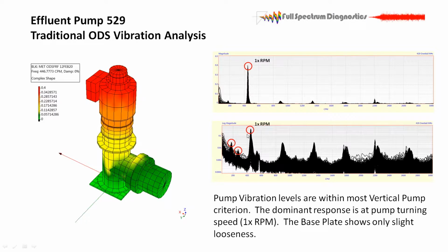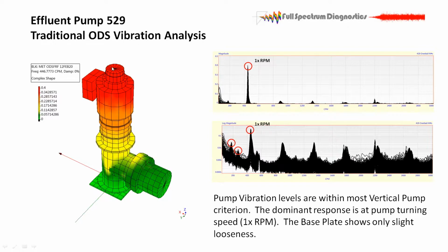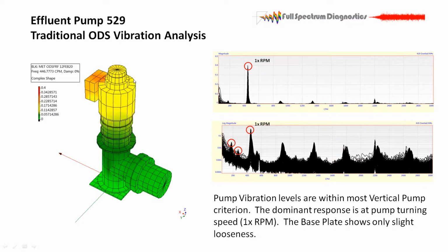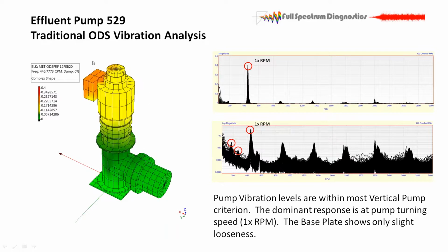So I think there's a natural frequency in here. That's one indication. You got a broad peak, that's another. And the motion itself is very linear. If I have just residual unbalance, this motion will be a whirl instead of a linear vector like that.